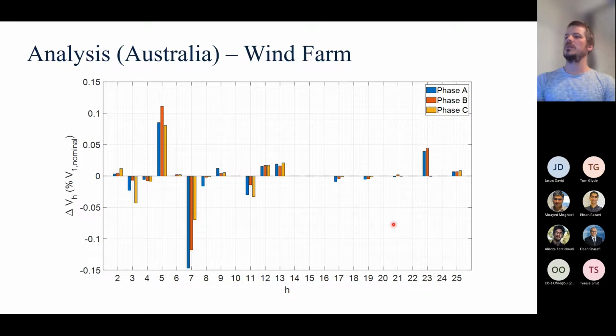And so we found the 95th percentile distortion values for each individual chunk, did that in isolation. And we looked ultimately at what the 95th percentile values were doing pre and post connection of the wind farm. Simple as that, nice and easy. Didn't dwell down into transients and instantaneous impacts. Just looking at high level, what might we be able to expect when we connect?